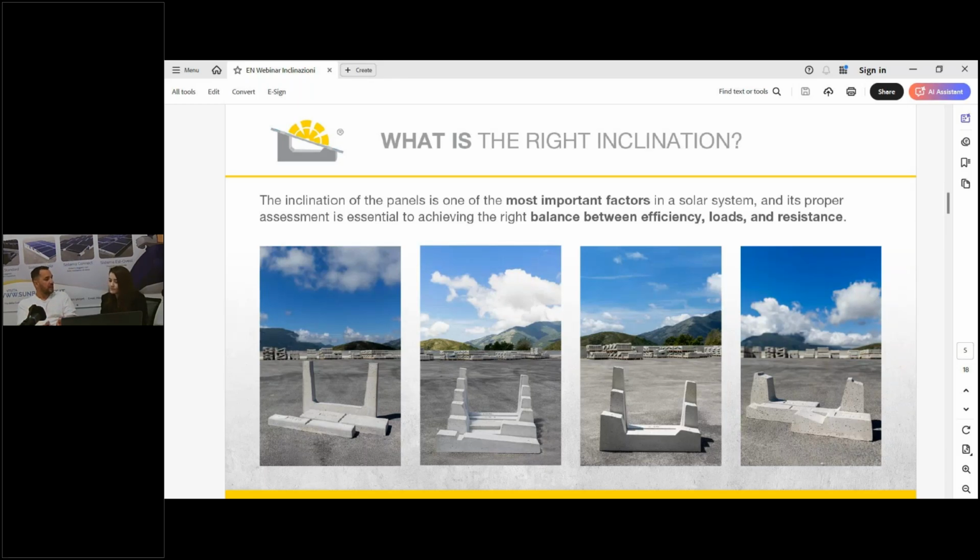We always say that we are mainly for flat roofs, but some ballast can be used on different types of surfaces, right? It can be used on gravel, on different pavements, with tiles, and on TPOs, EPDMs, all different sheets. That's why we have the rubber mat sheet that you mentioned, which plays a very important role to protect the roof material and also to protect the ballast from going deeper inside.